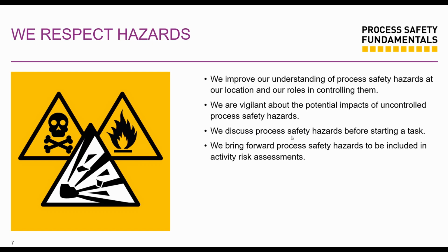Any task, you want to break open a flange, you want to start up a pump, you want to clear out a strainer. Be aware of the hazards that arise from that task. And also bring process safety hazards to be included in activity risk assessments. So this is the first one.